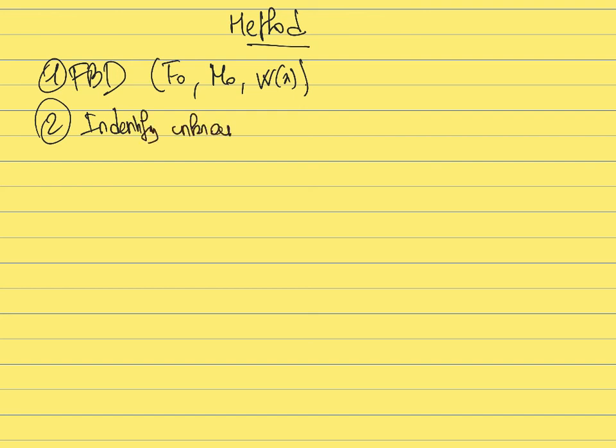You need to identify all the supports and identify how many unknowns you have. So this is still the same. Step 3, you need to use the condition of equilibrium to calculate the unknown.